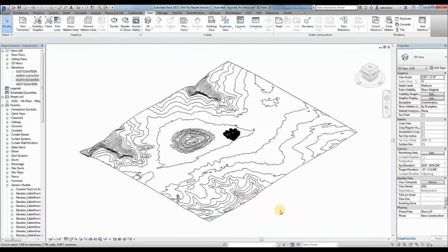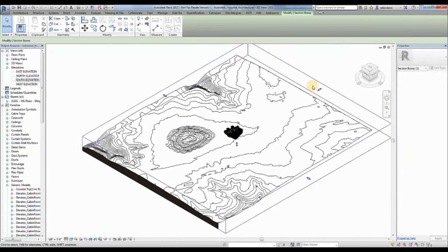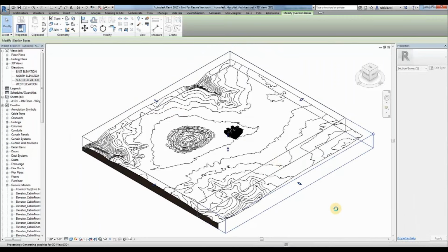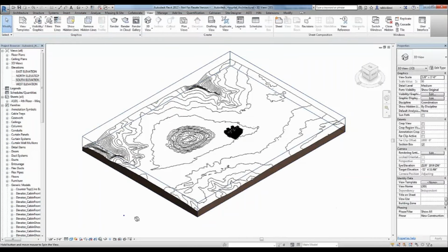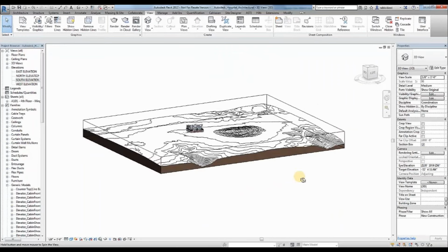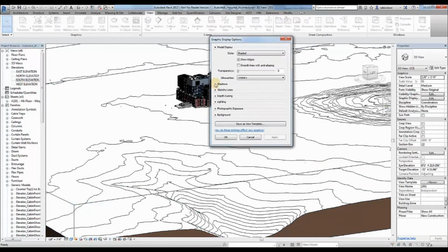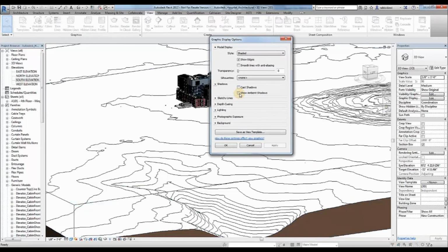Once the elevation is set, then you can set a section box around that topo, and you can even edit it and create slight modifications to the topo. Let the civil engineer do the major modifications, such as the road design and any water detention areas. But when it comes to the immediate vicinity of the building, you want to be able to work with the building pad and sidewalks, any stairs and ramps, and coordinate connections to the building utilities.